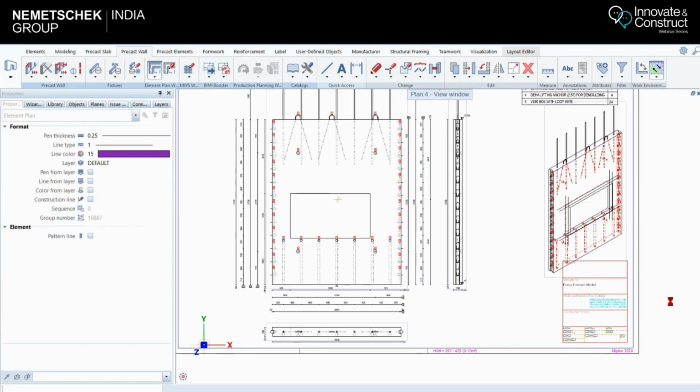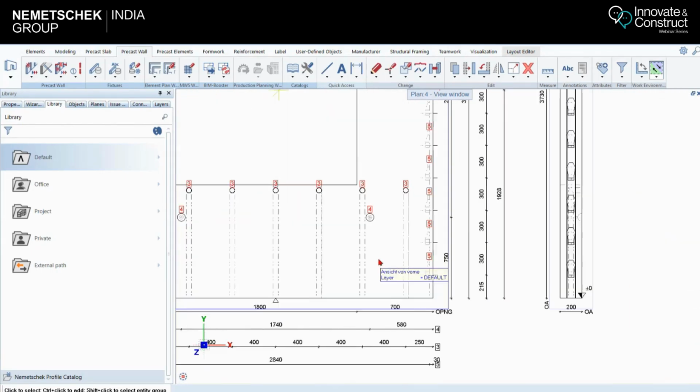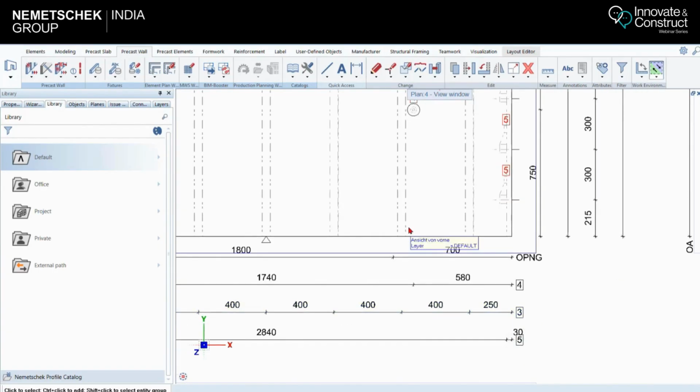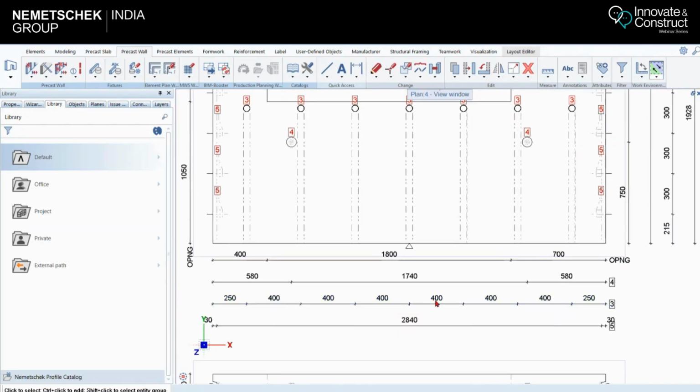With the model, we are also getting, as we have seen, the bill of material as well as the complete dimensioning. If any fixtures are added, removed, shifted or modified, it will automatically change the things. Let's say, for example, here we have added some grout tubes, which are at a distance of 400 mm each.